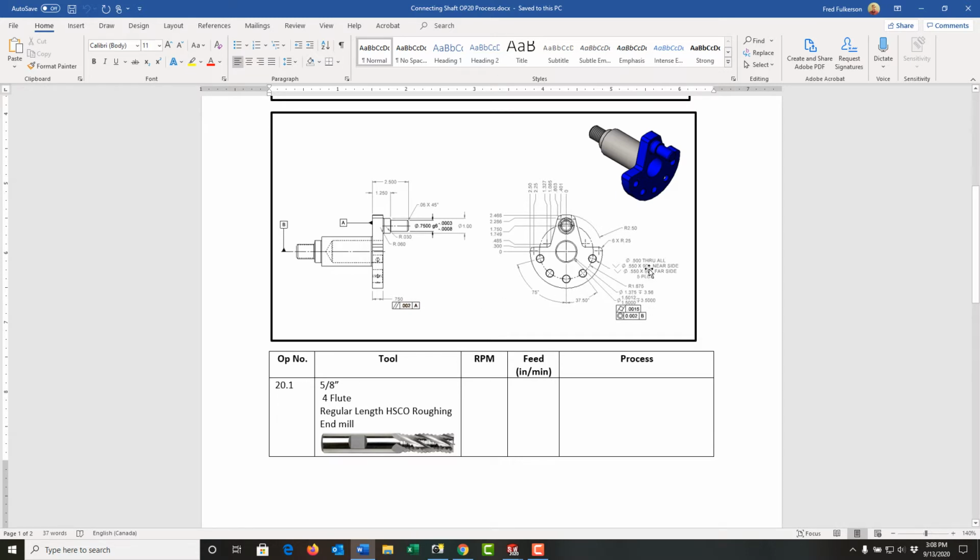So if we focus just on these holes, they could be made before we machine this face to size. However, if we do that, we're just going to push a heavy burr down into the hole. Again, this hole could be made before this face is machined, or this face could be machined and then this hole. These are independent. Machining around the outside profile here is independent of machining any of the holes or even this feature. But we want to consider our process, how we leave a burr. Does it get pushed over? Does it get removed? Is it more work later to deburr the part?